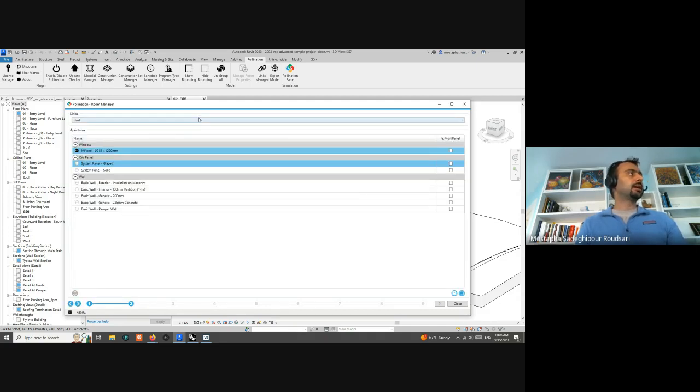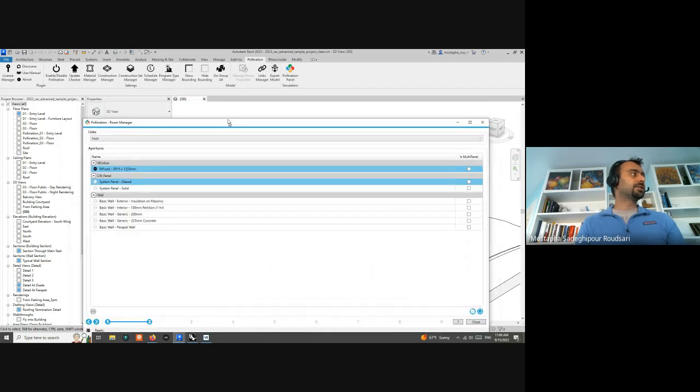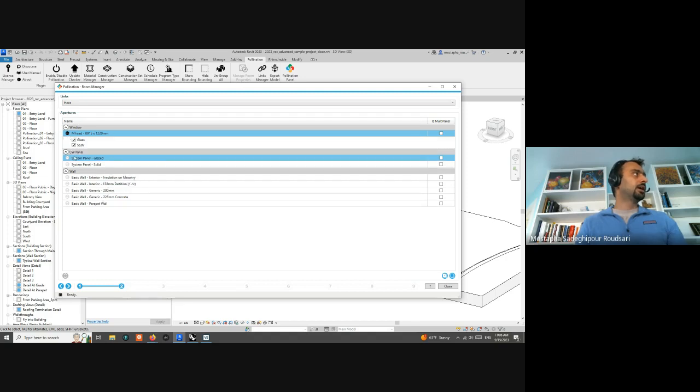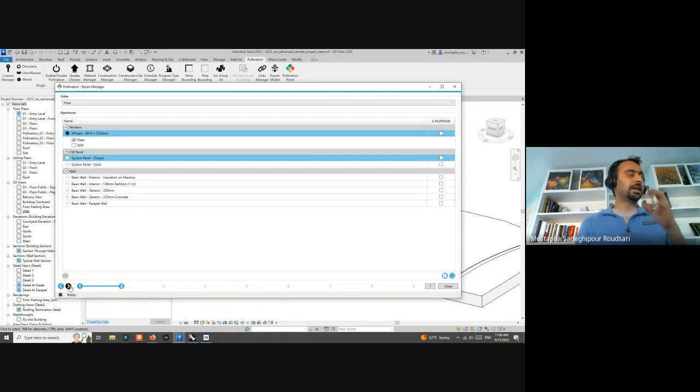Then the next step is the place that you basically set up what apertures, and what are the windows and curtain walls that should be considered apertures. We have seen people using walls for apertures. That's why it's available here. So you can select from any of them. You can also select based on material and filter even more. So that's one of the things that we do, right? We just let you pick what the model is more than trying to guess.